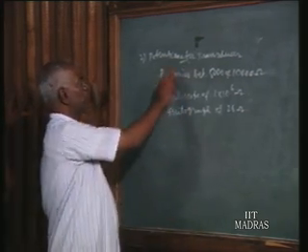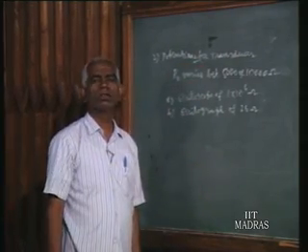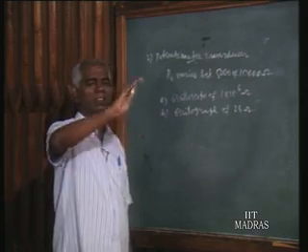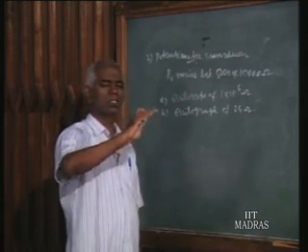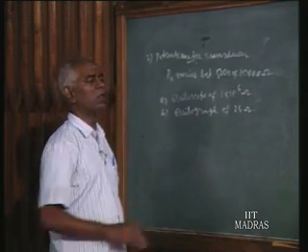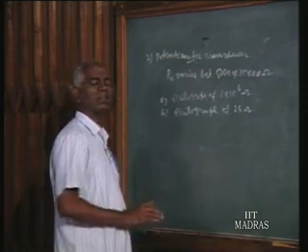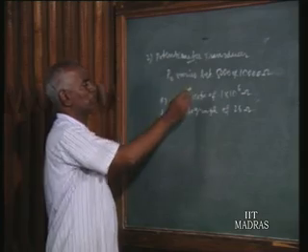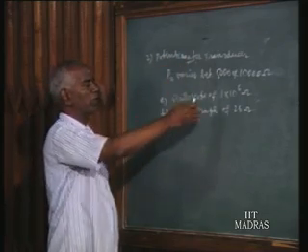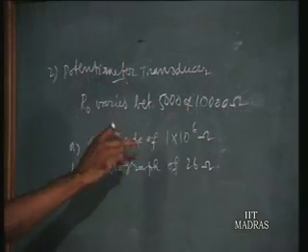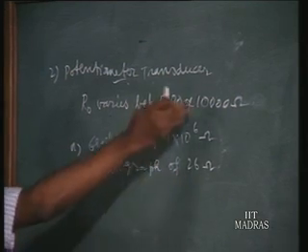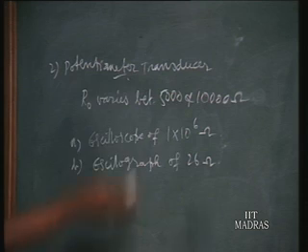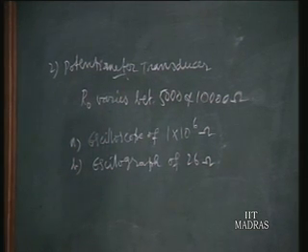Now we have already seen for a potentiometer transducer, the output resistance of the potentiometer circuit varies as the input displacement varies. In that case, the loading effect is going to vary. That is what we learned there qualitatively, but now we are going to see quantitatively. Now RO is, as the displacement is moved within the potentiometer between points A and B, at point A it is 5000, at point B for example 10,000 ohm. Here you are not asked to find out the RO, the values are given in the problem itself.